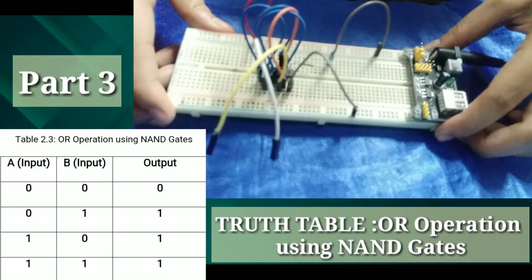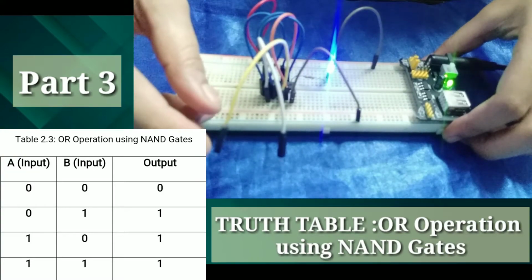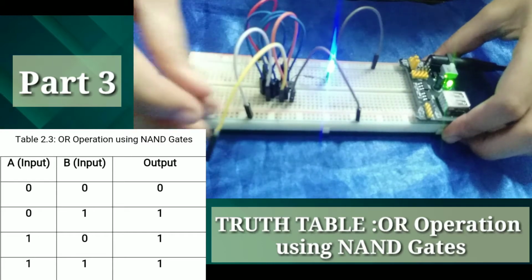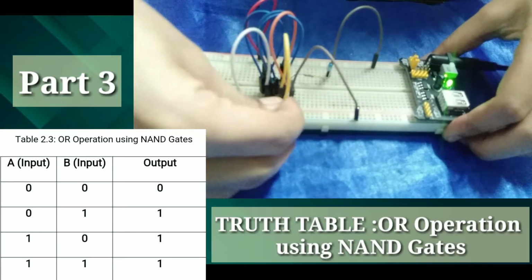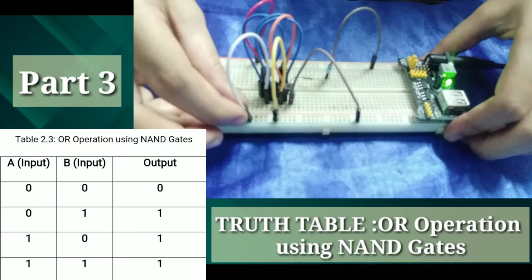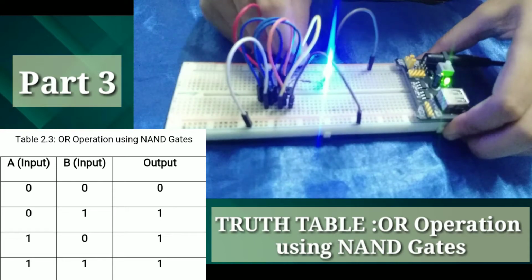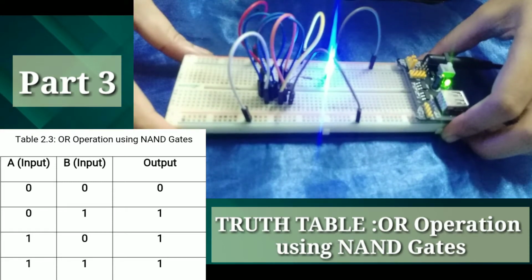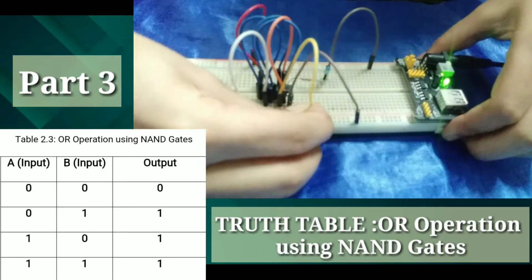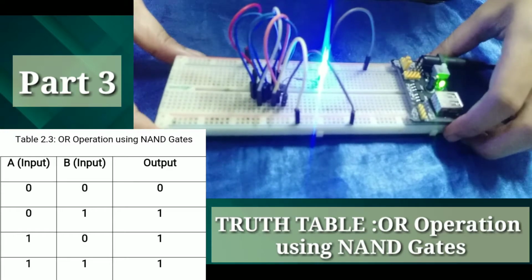Now, for our truth table, let's turn on the voltage supply. If input A is 0 and input B is 0, as you can see, the light is turned off. If input A is 0 and input B is 1, the light is turned on. If the connection is interchanged, B is 0 and A is 1, the light is turned on.